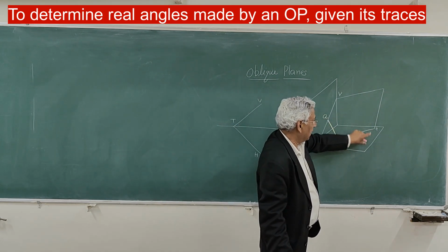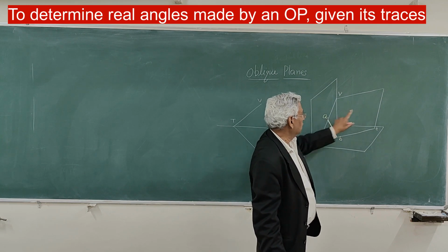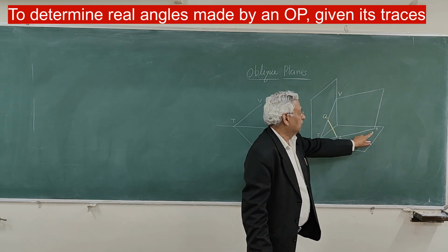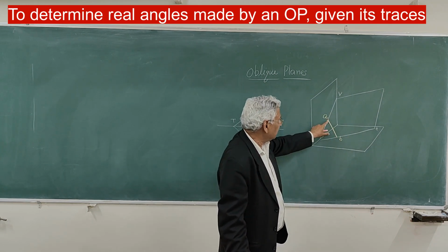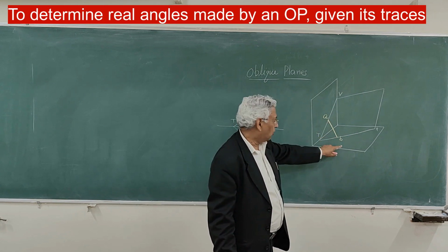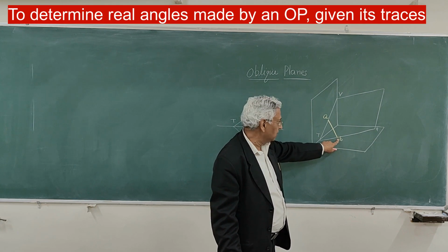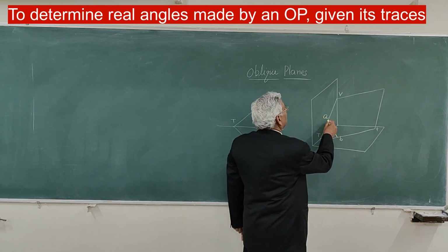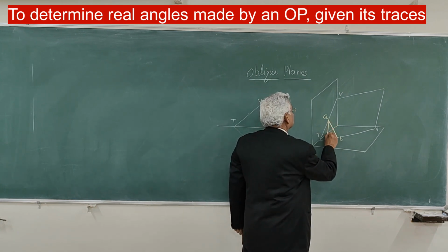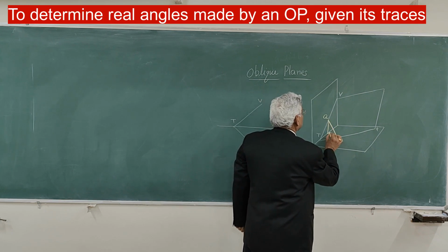Now this is plane number 2, and this is plane number 1. So in plane number 2 you draw a line AB perpendicular to the intersecting line, and get the projection of this line on this plane. Now this point is in the horizontal plane, so this is the plan itself, and the point in the vertical plane has its plan here on the ground line.